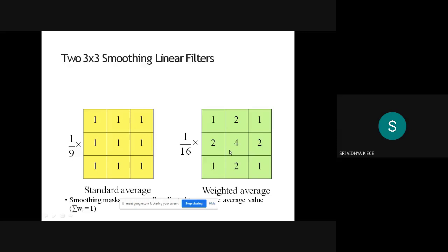These averaging masks, as we do normal averaging or normal mean, cause smoothing of the image. Somewhere you will have high intensity noise pixels, somewhere low intensity image pixels. Say 40% noise is there and the remaining 60% is signal. This 40% of noise will be distributed throughout the remaining image, so the intensity of noise will come down. But at the same time, it is not eliminated, it is only distributed, isn't it? Because of that, it causes a smoothing effect, and sometimes even a blurring effect.